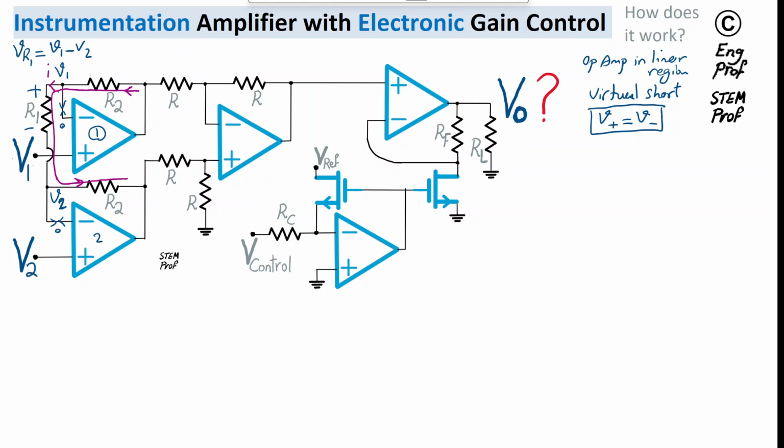So I can compute the voltage drop between these two nodes, which let's refer to as node X and node Y. So I can compute basically Vxy, which is Vx minus Vy, as the voltage drop across the series of R2, R1, and R2 in this circuit. So in that regard, I can say this voltage drop is simply current I times (R2 plus R1 plus R2), which effectively is I times (2R2 plus R1).